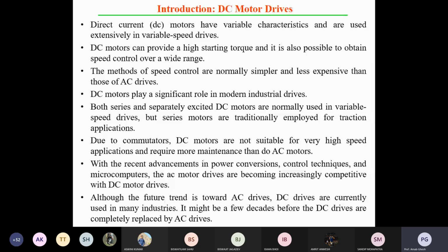depends on which controller you are using and the zone of operation, means for which duration you are controlling. One half cycle is 180 degrees. For the selection of the firing pulse, you can keep the pulse anywhere from 0 to 180 degrees. If you distribute the range into 18 divisions, one division is 10 degrees, and 18 divisions make 180 degrees. If you make it 20 divisions, one division equals 9 degrees, and 9 times 20 is 180 degrees. Then definitely the sophistication is more.